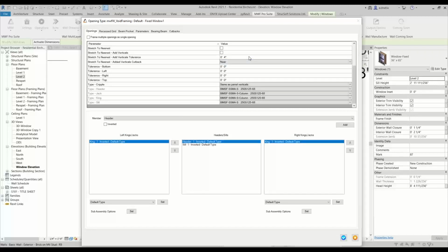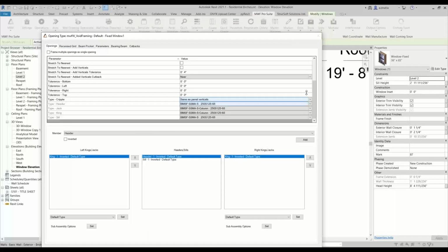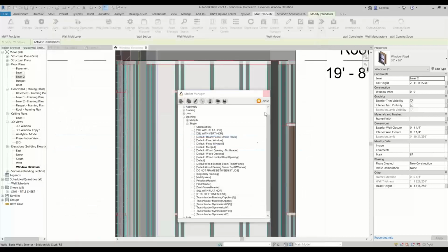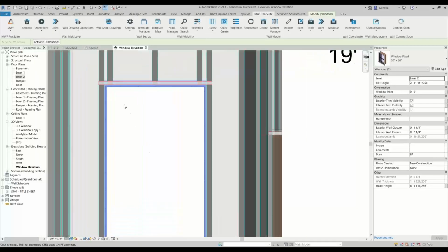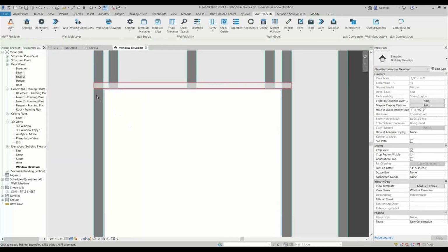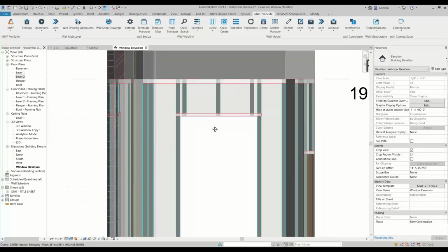No? Okay. So now we have these tolerances over here. I'm going to close out of here so I can show you the dimensions for a quick second. Whenever we want to go into the opening, I'm going to hide this opening here. We want the framing to go towards the center of the opening, so we are going to use negative dimensions. If we want the framing to go outside the opening or away from the center of the opening, we will be using positive dimensions. All right.